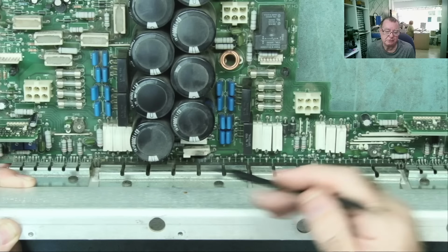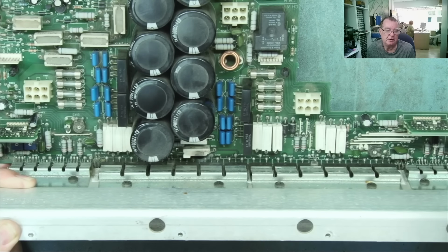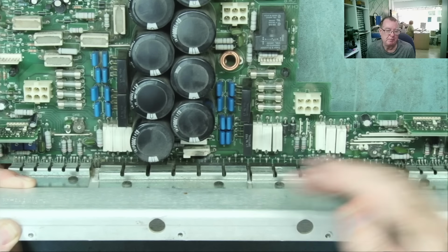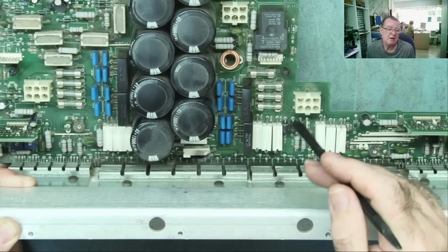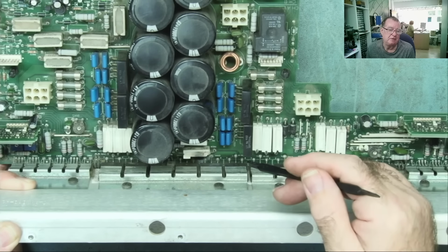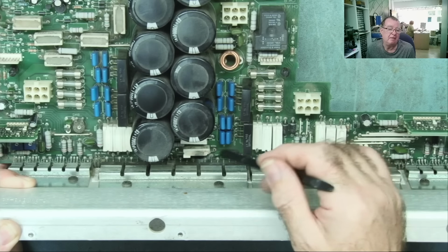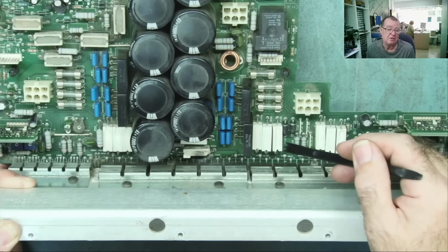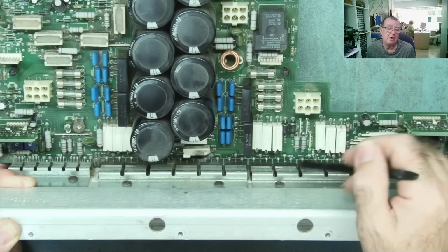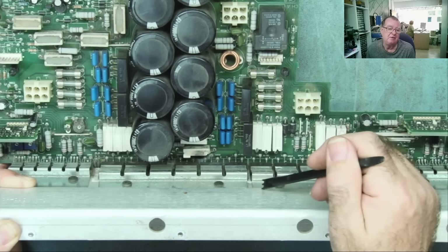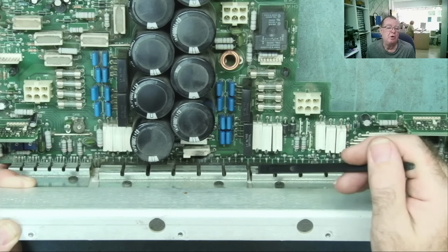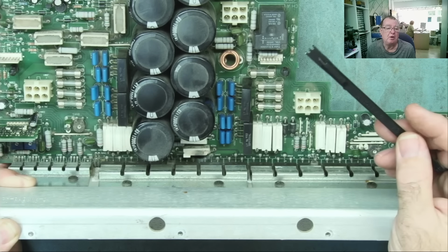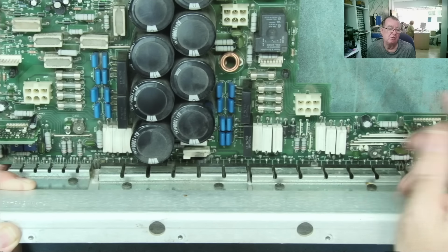But once you find short circuit power devices on an output, you should do at least 3 things. 1, obviously remove and replace the devices. But before you try this again, 2, have a look to see what is driving those devices, because the chances are, if you have a short circuit in the output device, which is often operated at high voltage and certainly high current, the high voltage can then go back into the circuit to whatever is driving it and cause a failure there. So you need to work your way back from the short on the output that you find as far as you can until you find components that are no longer damaged.